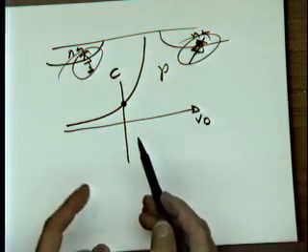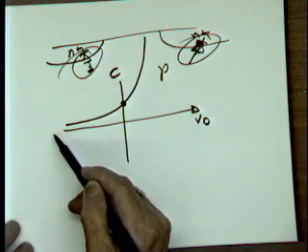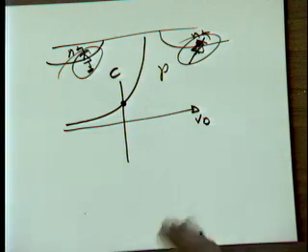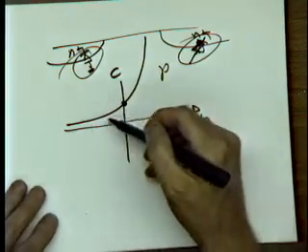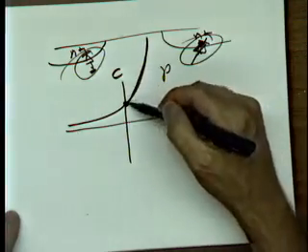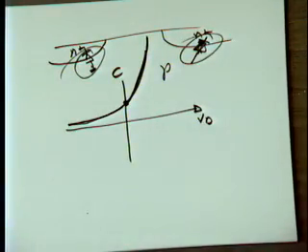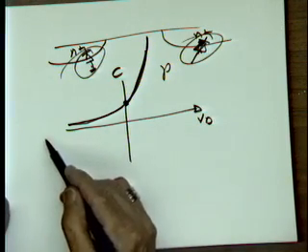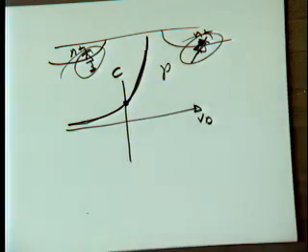You can see that if you go more and more reverse biased, the capacitance gets smaller. Sorry, you get a thicker and thicker depletion layer, and that's why the capacitance goes smaller. So with very heavy reverse bias, you have very small capacitance, but then you go forward bias and you see that the capacitance actually goes up substantially.